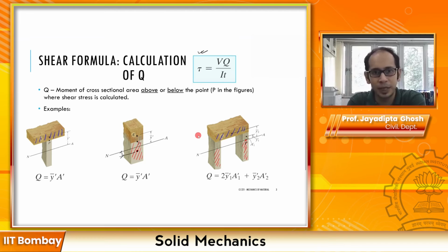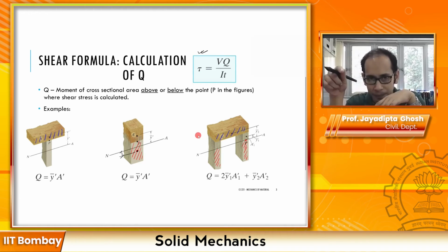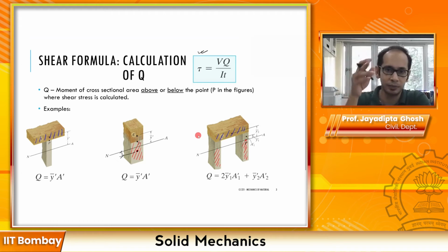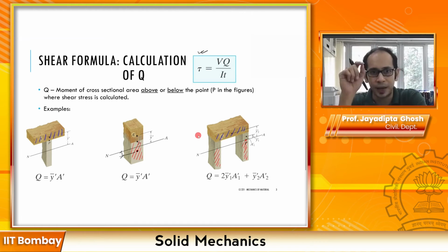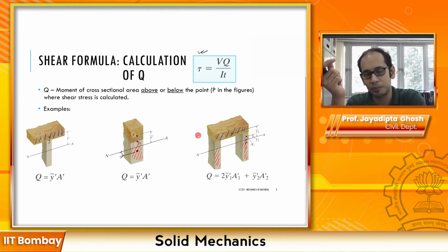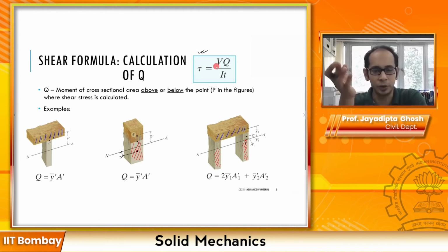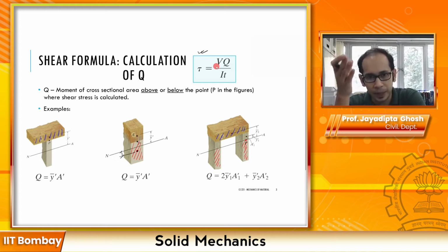We'll look at one very simple example and another slightly involved, where you have to make use of a shear force diagram. Remember that for bending, sigma was maximum within a section at the top or at the bottom, but within a beam it is maximum at the point where the bending moment is maximum. Similarly, tau is maximum at the point where your V is maximum. So essentially you have to find the place within the beam, from your shear force diagram, where the V is maximum.